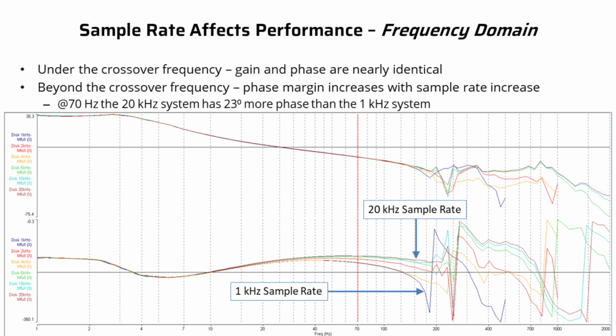And so while I proportionally change the gains to have exactly the same response, what this tells me is, oh, I could raise the gain of the 20 kilohertz system way more than I could raise the gain of the 1 kilohertz system. And if I raise the gain, I'm going to move the crossover frequency out, and I'm going to increase the bandwidth of the system. I'm going to have a better response. So as formulated here, I have an identical response, but what you can see from this is I have the ability to increase the bandwidth of the 20 kilohertz system beyond what I can with the 1 kilohertz system. And that produces better performance of the system.